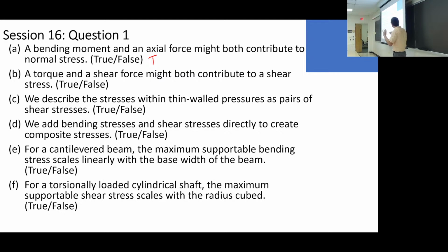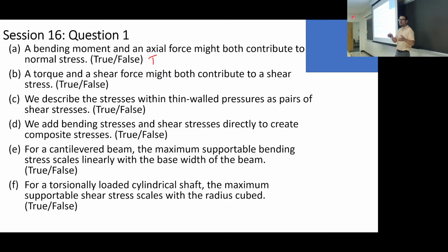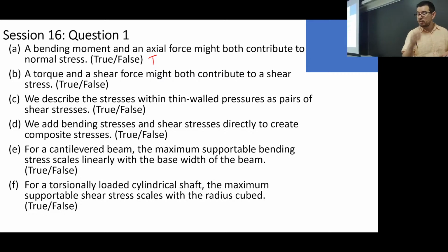That's contributing shear stress. What about a shear force? Where have we talked about shear forces? Mostly internally, but we've talked about them in double shear now, and in beams. Shear force typically is an internal construct. That's the V. So does a shear force contribute to a shear stress? You betcha. If we can figure out the average shear stress on a face on a beam internally, that's just the shear force divided by the cross-sectional area.